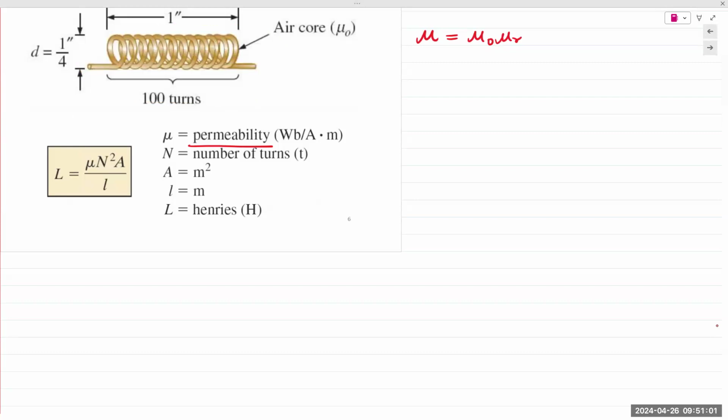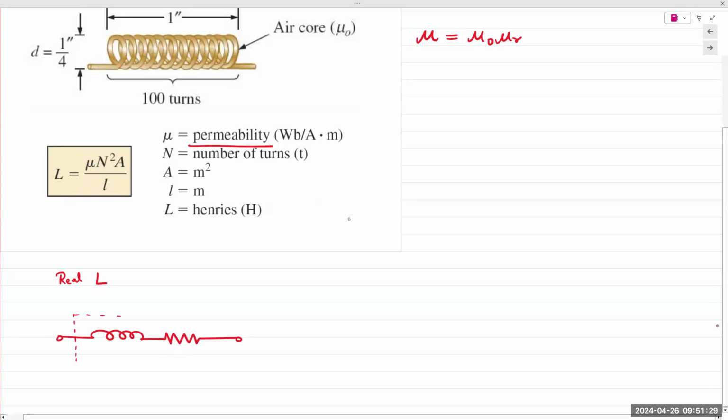If you measure the inductance, it'll give you a value for the inductance. If you measure the resistance, it's going to give you the value for the resistance also. But physically, it's the exact same coil. You cannot separate it out. So a real life inductor can be modeled as an actual inductor in series with that resistor, and this box comprises that inductor.